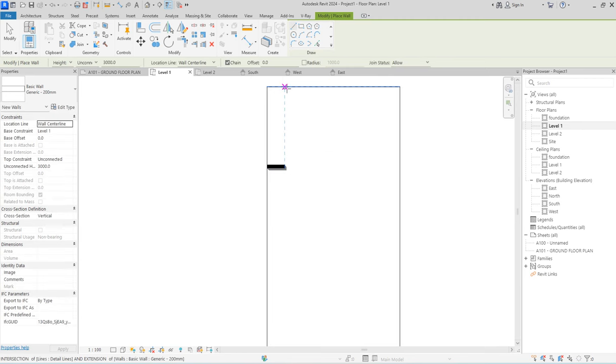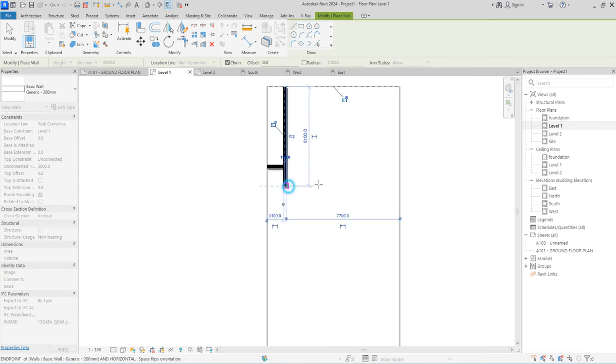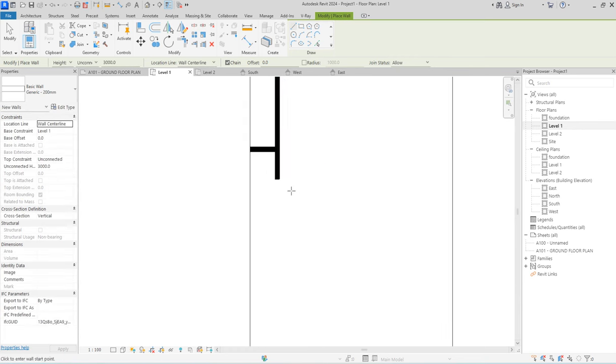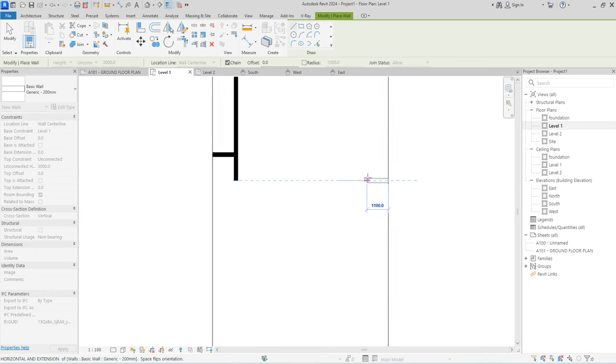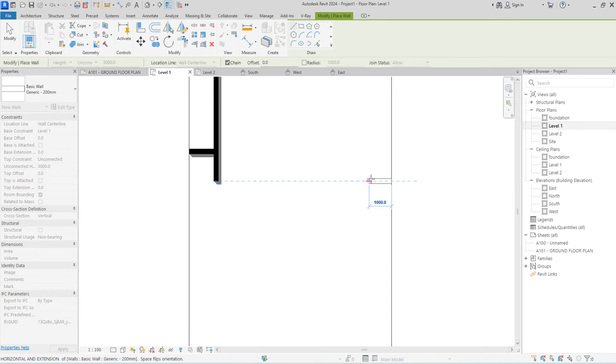So you take a 1.2 meter offset from here and check it, and then you draw. From the back, because of the swimming pool issue and every other thing, you can just have like a 6 meter setback. In other words, your building starts from here. So you take this one again, very important, 1.2 meter, to be precise.